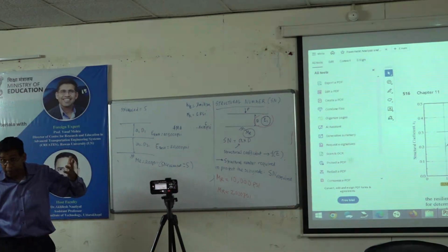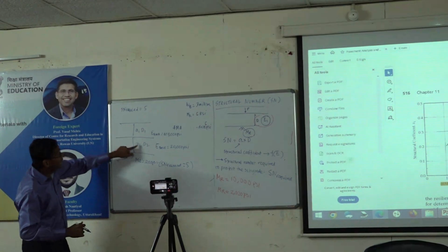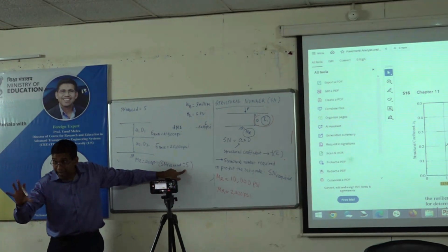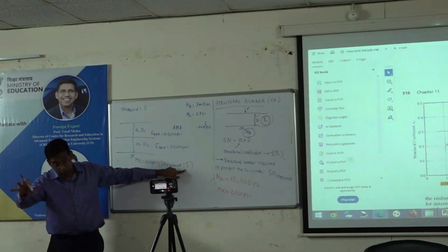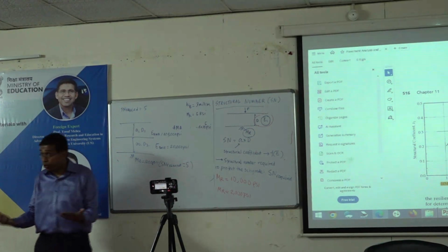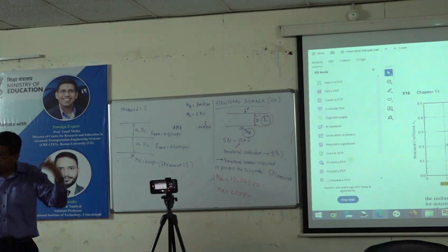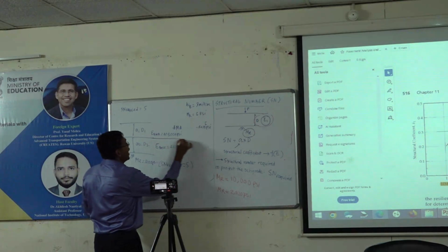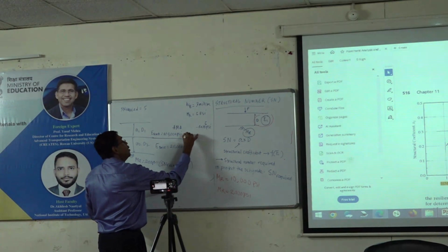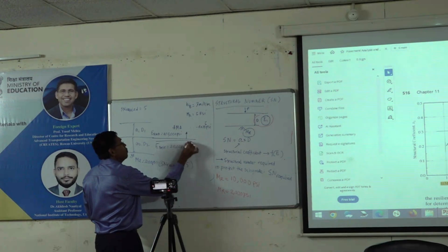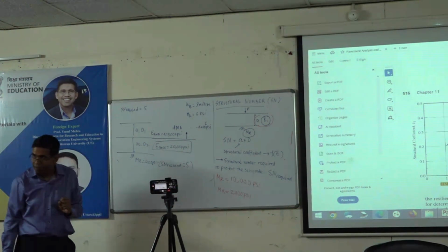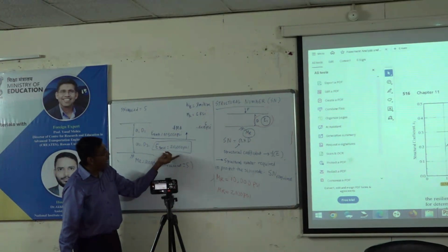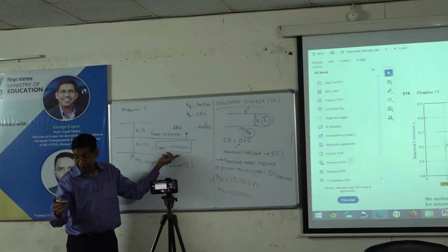I'll get the number 5. Right? Because A1, D1 plus A2, D2 should be greater than 5. Fair enough? So the whole thing has to be greater than 5: SN provided by A1, D1 plus SN provided by A2, D2. But how do I do this? You start from top to bottom. So right here, what is my SN required to protect this base? I have to calculate that first.